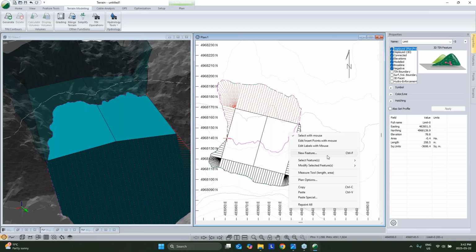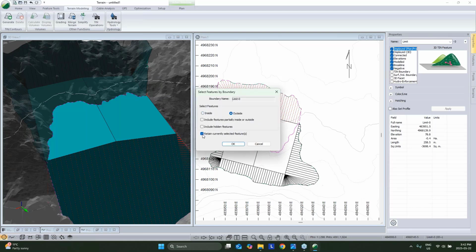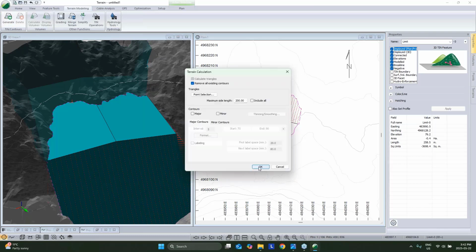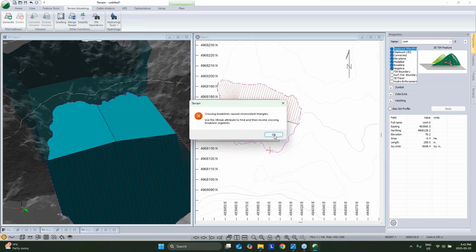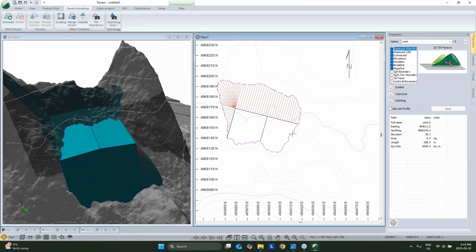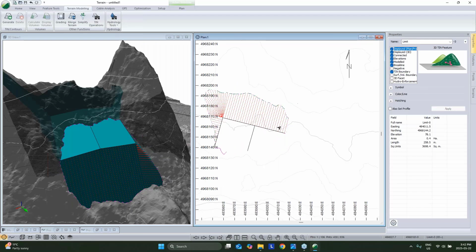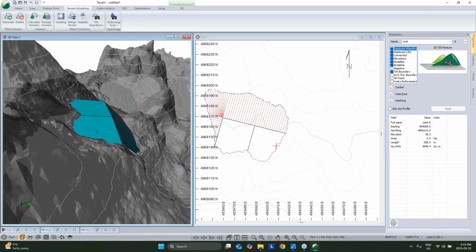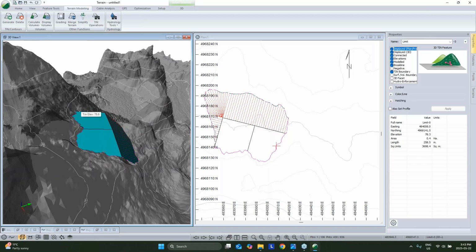And I'm going to get rid of everything outside of that feature. So select by name, by boundary, outside. And now we're going to... oh, I've got the wrong button set. There we go. Yeah, I want it to be a tin boundary, not a negative. And there we are. So now we've just clipped that where we intersect that other surface.